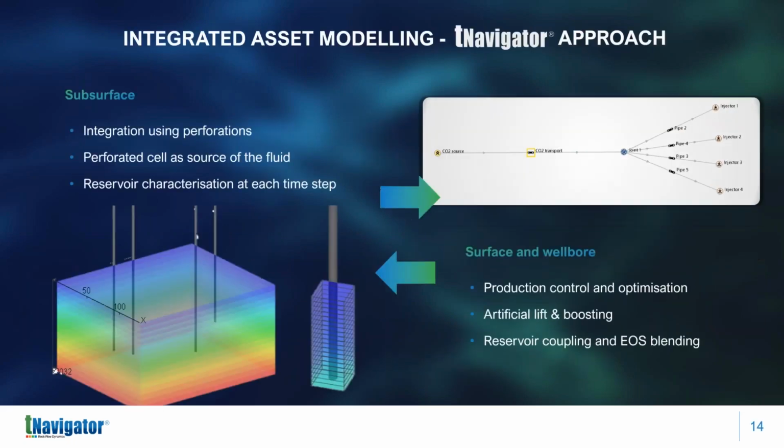Finally, going to the last few slides. As I said before, in our approach we have a proper integration between the subsurface and the wells. We can specify the well perforations in the well designer, and we can integrate the reservoir model, and we don't need to apply any additional controllers to run the integrated model. So we can basically control CO2 injection from the surface level, using pressure and rate constraints on the surface level to run the model.